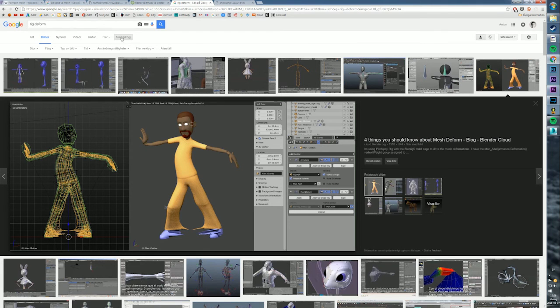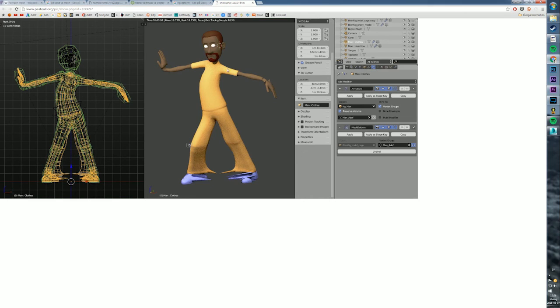Also, when it comes to polygons, they are much better to work with when it comes to, for example, modifying, animating, rigging. So in this case, if you want to control, let's say, a movement, it's much easier to control a few polygons than to control an infinite amount of math, which would be a solid or a surface model. So you don't animate surface models. You create a polygon version of it with the resolution that you want. Let's see, this is quite a low polygon, and then you smooth it. So you do the control before you smooth it, and then you have a smooth model that you can control with the easy bone structures and so on.